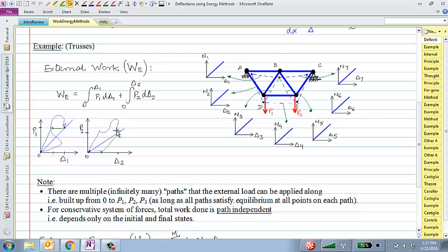And as these two external loads P1 and P2 do work on the structure, it is going to store energy within itself, just like I was doing to this column. This column, I apply a load P, and in this bent configuration, in this deformed configuration, it is storing a lot of energy, right? It's behaving like a spring. As soon as I leave it, it wobbles back and forth. So in its deformed configuration, this structure has stored a lot of energy within itself.